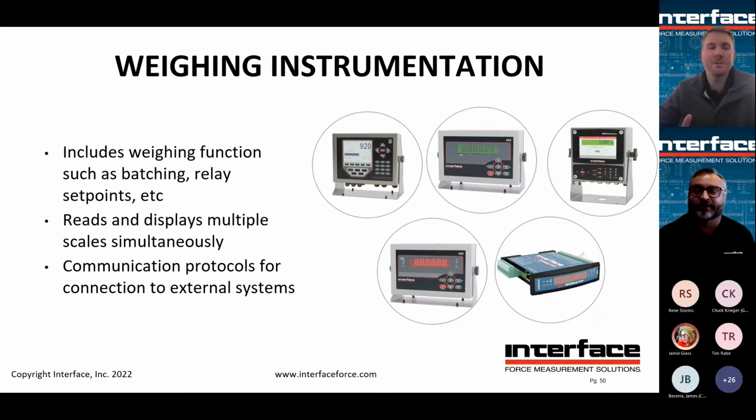So weighing instrumentation. Back to Jeff. So typically referred to as indicators, but known by many names: scale head, weight display, controller, or simply where the numbers are. They're essentially the power source of the scale and can perform a multitude of functions. Some of them can sum up to 32 scales in one indicator, not recommended, but capable. A number of field bus options: Ethernet IP, Profinet, Modbus. Pretty much talk to about anything, any PLC or PC on the market today.